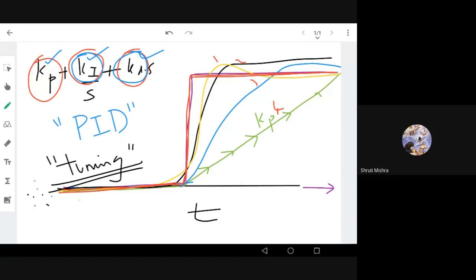And we already discussed yesterday in the tank example, the output of the controller may not have the same physical relationship with the output of the plant. The output of the controller was the controlling of mass flow, that is mass of the water in unit time flowing into the tank. If it is positive, it means the water level is increasing. If it is negative, it means water has been drained out of the tank. So that is what the controller is controlling.